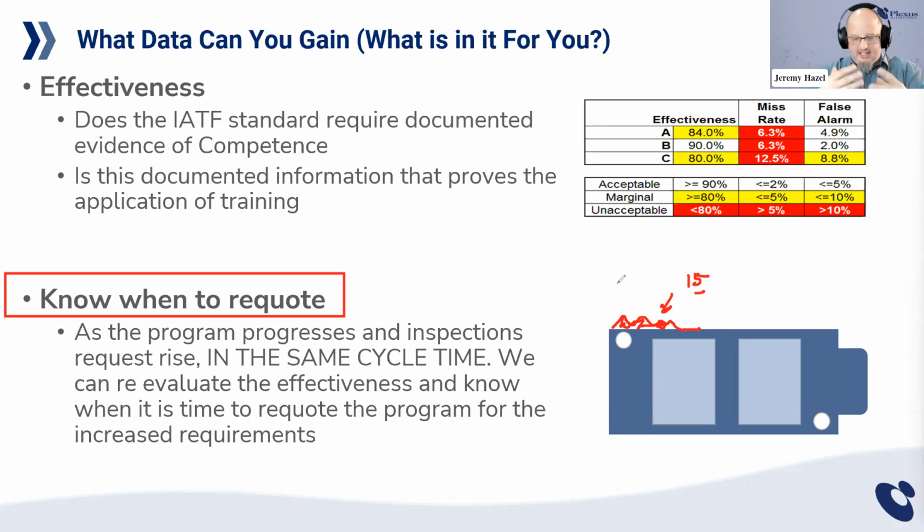So the operator would take this flash. We did the MSA. Some parts were perfect. We had trimmed them clean. Some parts were gross. You could see the wing hanging off it, right? And a lot of the pieces were in the gray. We gave them 15 seconds and we got back good effectiveness, right? Now, here's the trick. Three months into the program, they wanted us to check for spray overflow of the plastic spattering in the filter area in the same 15 seconds.